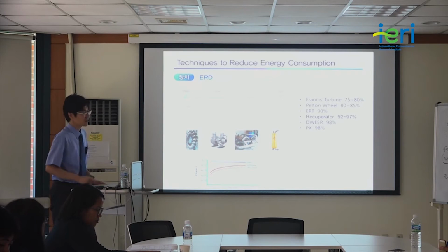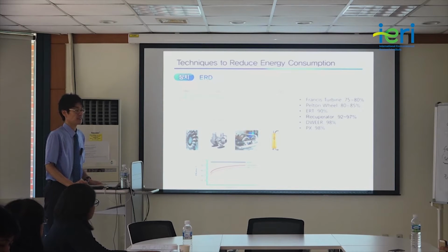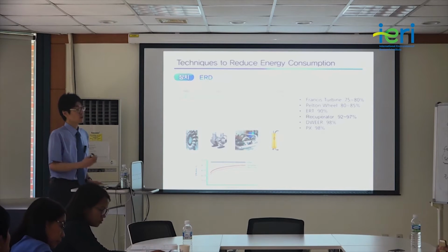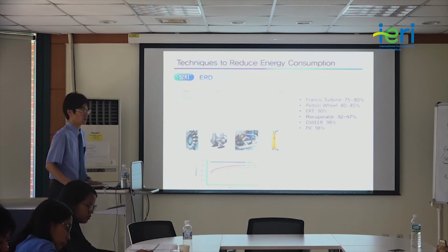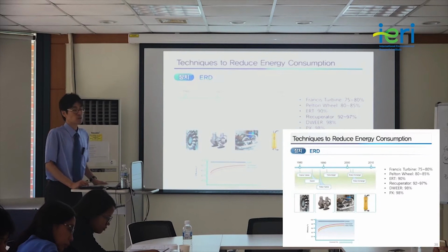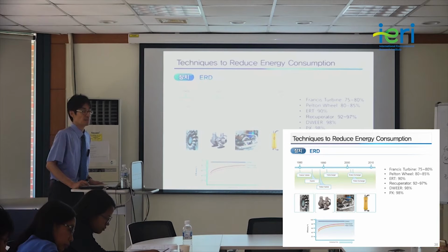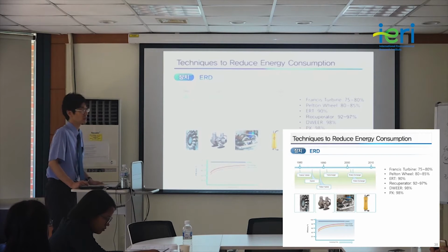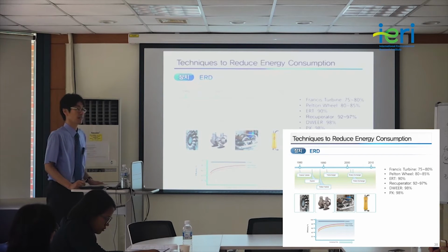And another very important device is the energy recovery device, ERD. I'll talk about that a little bit more with the following slides. But the reverse osmosis desalination system has had a very significant improvement and advances by inventing this kind of energy recovery device.